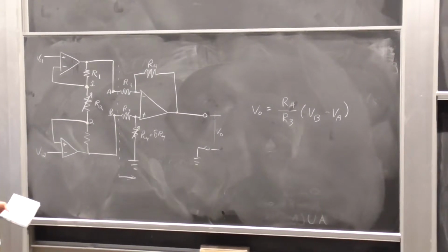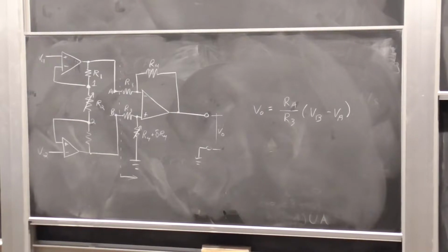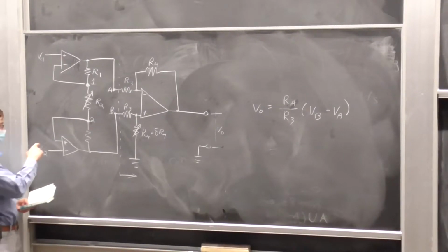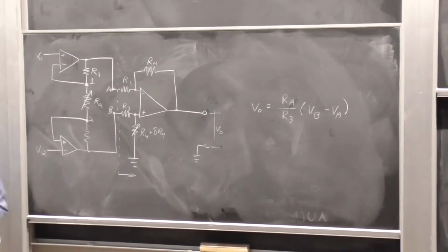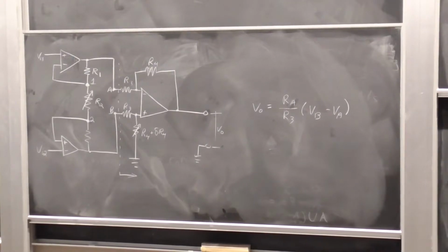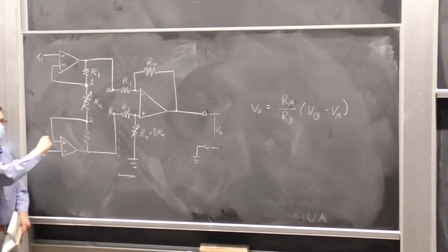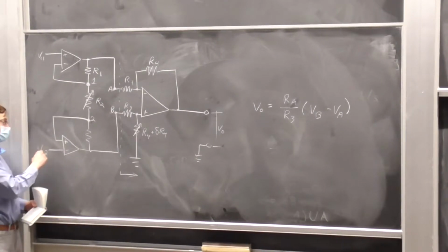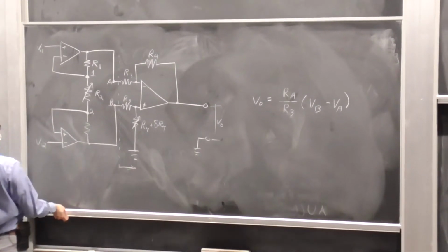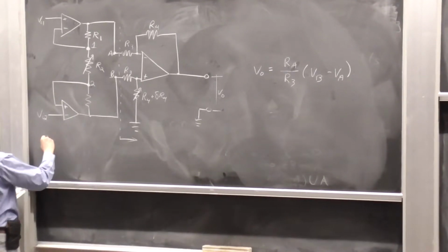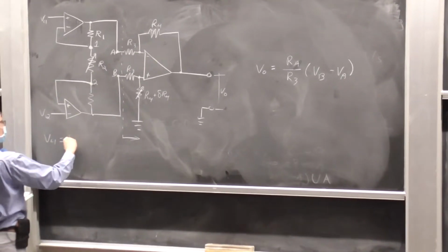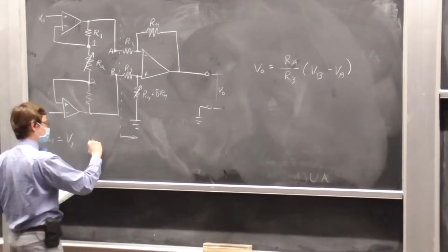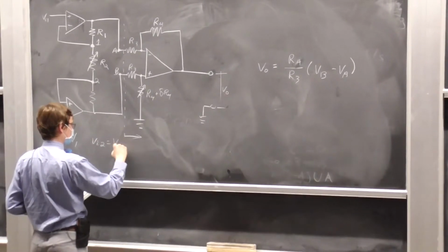We will notice, hopefully relatively immediately, that by the op-amp law, the voltages at both of the input leads are held to be the same. So, we can say, with confidence, VI1 is equal to V1 and VI2 is equal to V2.